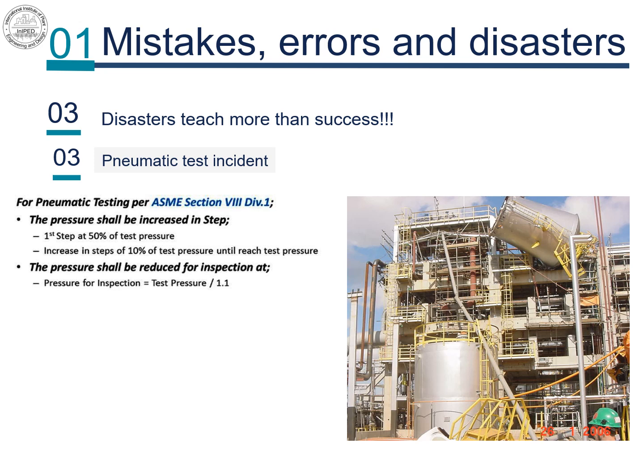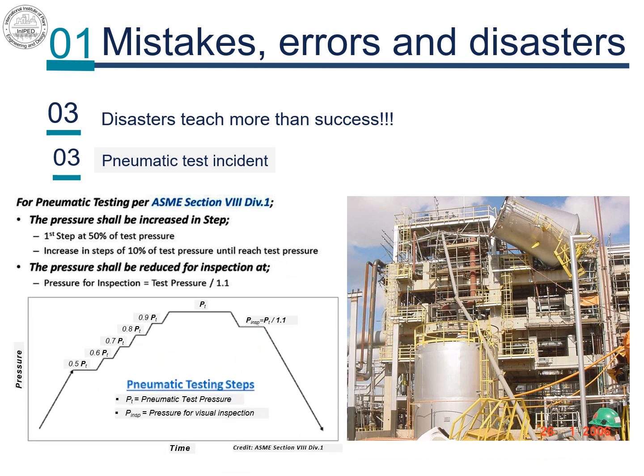In essence, the pressure should have been gradually increased until a gauge pressure that is the lesser of 1/2 the test pressure, or 170 kilopascals, 25 pounds per square inch, is attained. At that time, a preliminary check should have been made, including examination of joints in accordance with B31.3 requirements. Thereafter, the pressure should have been gradually increased in steps until the test pressure is reached, holding the pressure at each step long enough to equalize piping strains. The pressure should have then been reduced to the inspection pressure before examining for leakage in accordance with B31.3 and ASME Section 8.